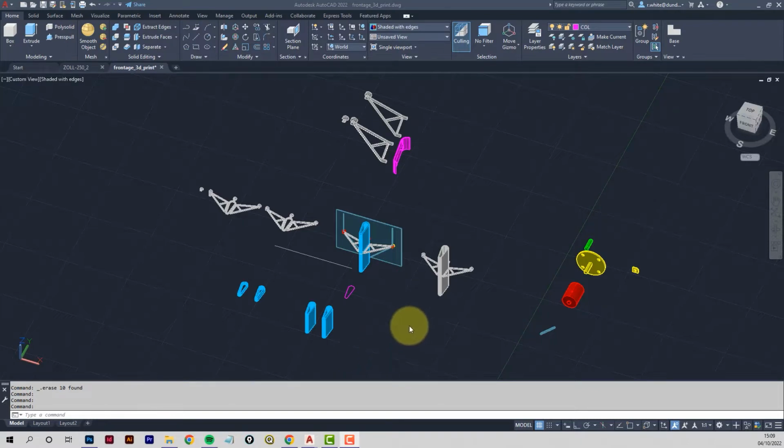But it really boils down to the model being in the correct format. Software like Revit is not intended for making models for 3D printing. It's intended for delivering a building on site. SketchUp, if things are done correctly, can easily generate models for 3D printing, but often there's material and bits of geometry left in that cause problems.